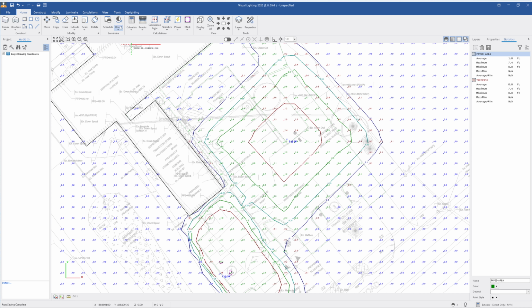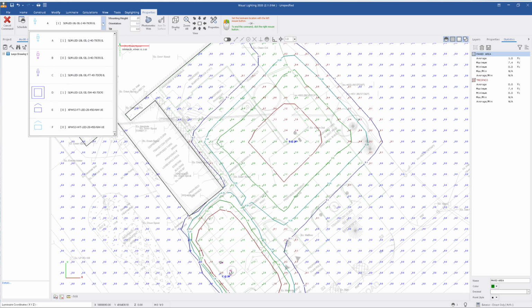So like I said, it's just a lot of trial and error. You go through, you pick your light fixtures. You have to really know your light fixtures or get used to what they're doing. In this case, I'm going to do some building mounted lights. They are usually located a little bit lower. So I'm going to put it at 10 feet, and usually there's a light near each door. So if I put one here, and it looks like there's a door here, and we're going to put one, let's say there's a door back here. Looks like there's a door here.